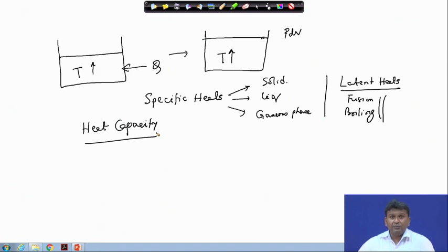But somehow we prefer to write Cp as the specific heat, as the heat required to raise the temperature of an object by a unit weight or unit mole of an object by 1 degree. So, kindly clarify this, because just the way specific gravity does not have a unit, we always write a unit to specific heat. So, that is not exactly fully correct. These things should be highlighted and people will feel very excited to know the nitty-gritty details, where at certain places what is used very commonly actually has some anomaly and things like that.